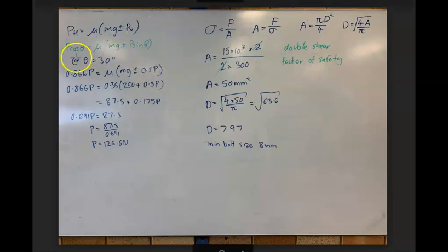And if you don't like the phony friction formula, what you can instead write is P cos theta equals mu times mg plus or minus P sine theta. That makes a lot of sense to use. It's a little bit more advanced and more difficult to remember. It doesn't have a mnemonic that helps you to remember. But what that does is it substitutes straight away the PH for P cos theta and PV for P sine theta.